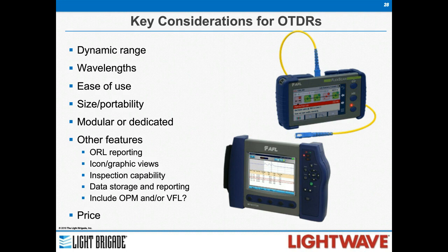The higher the dynamic range, the more you're going to pay for that OTDR. So it might be intuitive to say, let's just get as much dynamic range as we can, but you'll pay for that. So it may not always be warranted.